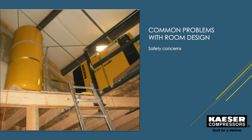That's quite a small ladder to come up and check on the compressor from a day-to-day standpoint, so certainly not something recommended. Obviously, you can build a different stairway to that area, but from a service standpoint, all the service for this particular compressor is done from the front, and that doesn't leave you a lot of room to do that service. Plus, if I had to walk up there and look at the screen, I'd be a little bit concerned as well. You probably need fall restraint, or if you're going to do service for that, change a motor or an air end on this machine, how are you going to do that?